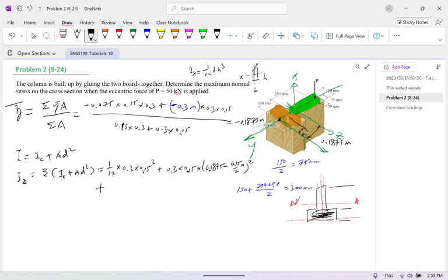And plus another one, the top one. Okay, also IC. So B is 0.15, H 0.3 cubed, plus area times the distance. Again, the distance we should mention to you, I say is here. Okay, that means here is 0.3 minus 0.1875 squared. So I will not repeat it because we will work it out here. Then we'll find it is equal to 1.5609 times 10 to the negative third power meter to the fourth.